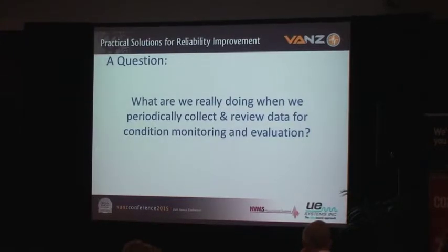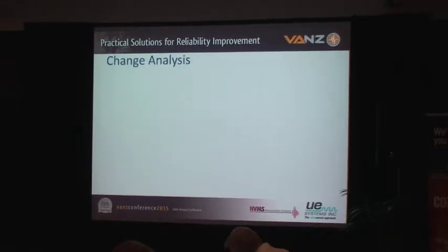I want to start with a question, and I would like this not to be a rhetorical question. The question is, what is it we are really doing when we're collecting data periodically, either with a handheld data collector, with an installed scanning or surveillance system, or even with a full-time continuous monitoring system? What is it we're really doing when we're collecting data periodically? And I'll give you a hint. One of the presenters yesterday focused his topic on what I consider to be the right answer to this question. Anybody? Looking for change. Bingo. Looking for changes. That to me is exactly what this is all about. It's change analysis.